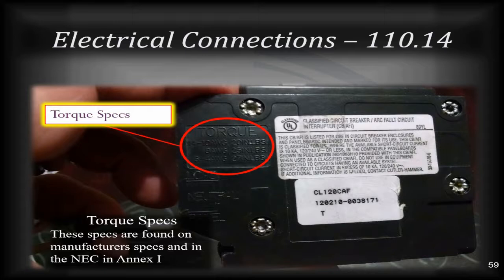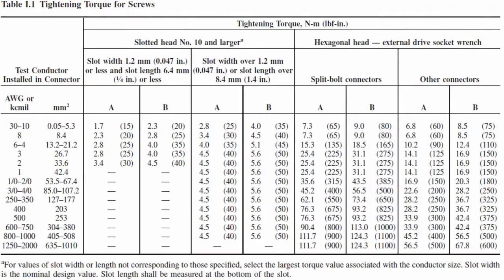Okay, if you're wondering more about torque specs, 110.14(A) speaks about them, and then there are other manufacturer specs that you'll find in Annex I. Okay, Table I.1 is your tightening torque specs.